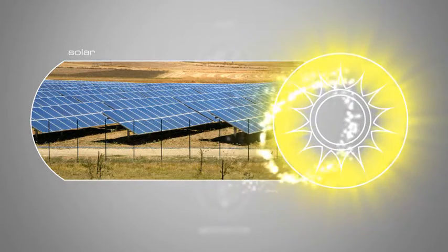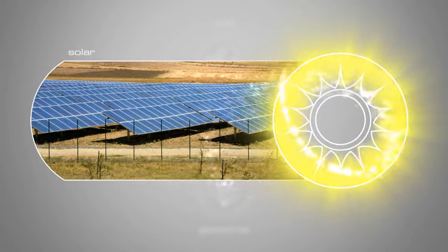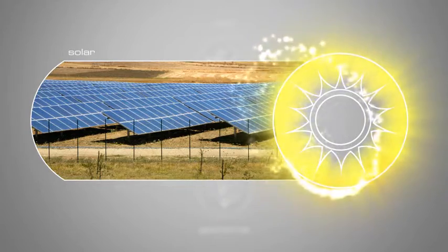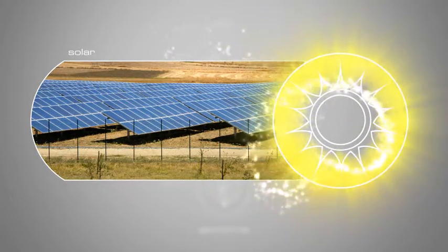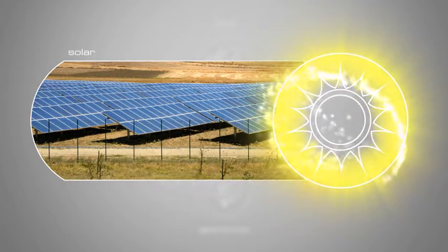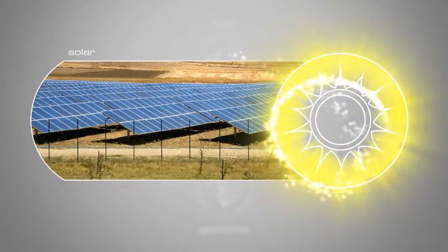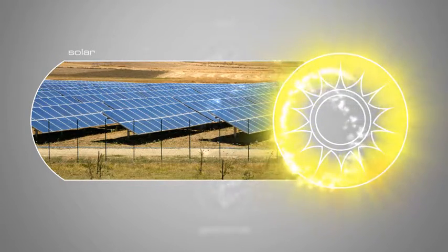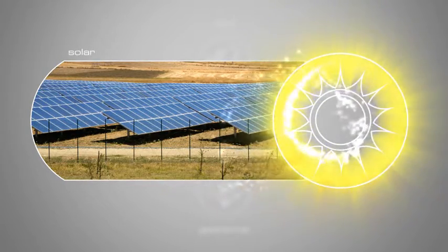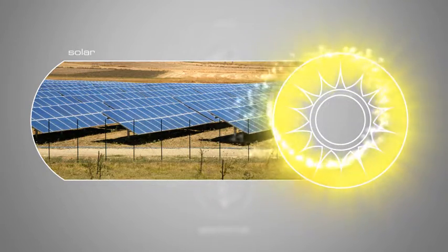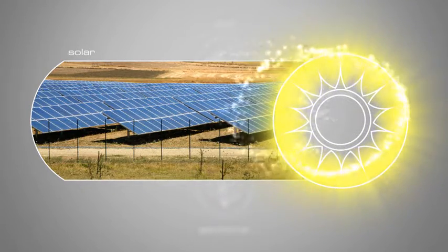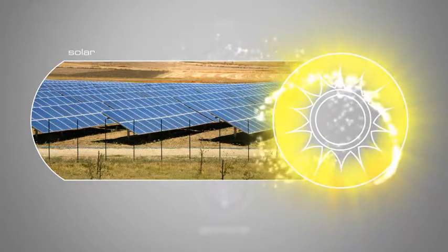Generally, temperatures above room temperature reduce the performance of photovoltaic cells. For best performance, terrestrial photovoltaic systems aim to maximize the time they face the sun. Solar trackers achieve this by moving the photovoltaic panels to follow the sun. The increase in efficiency can be as much as 20% in winter and 50% in summer.